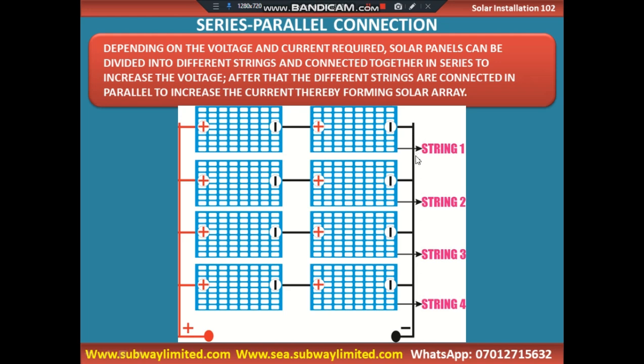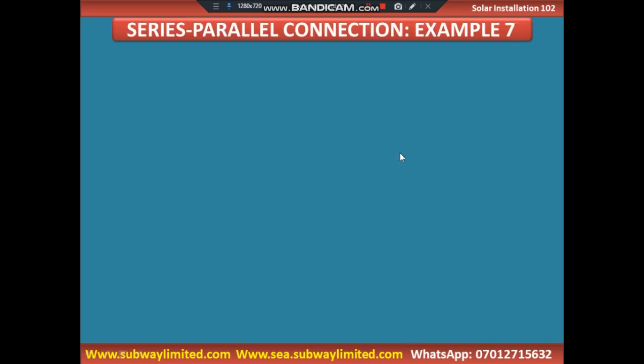And we later connect all of them in parallel by linking all the negatives together. And we connect all of them here by linking all the positives together. And we have an output here. That is series parallel connection. We first of all connect them in series, and we come and connect them in parallel.